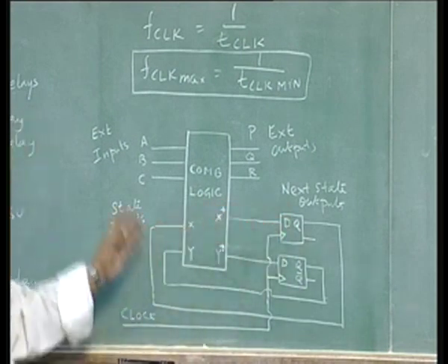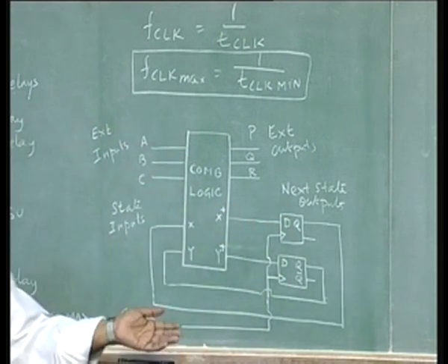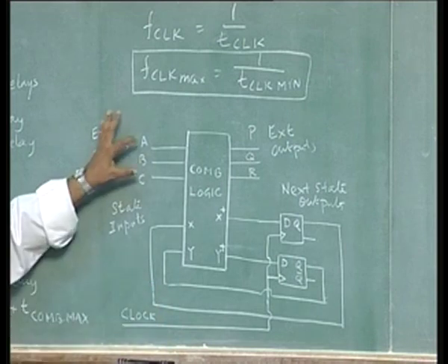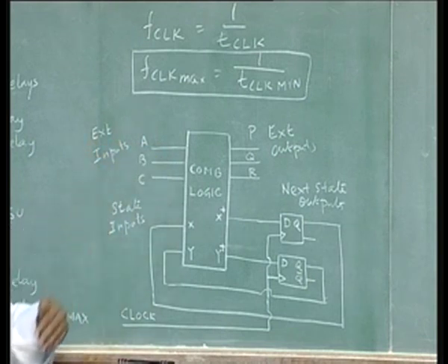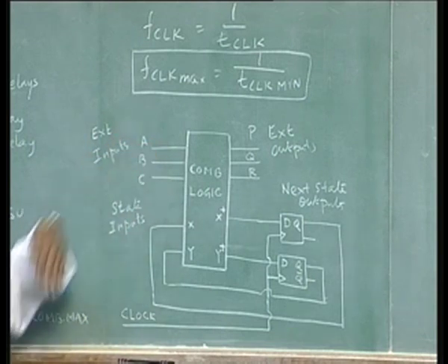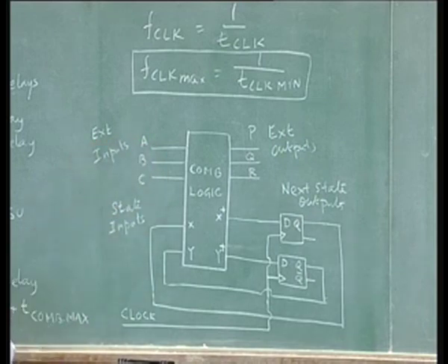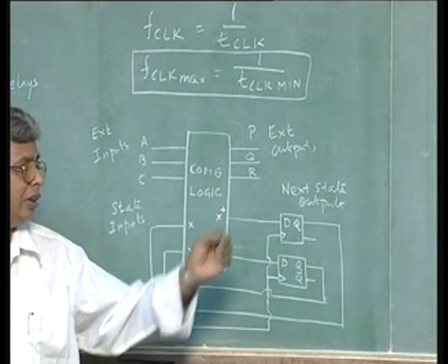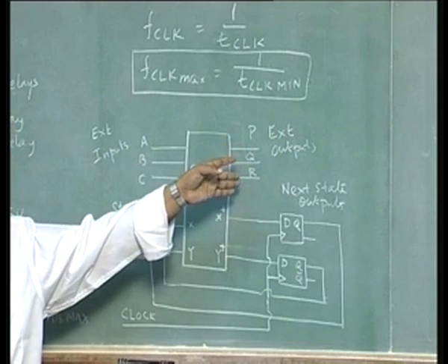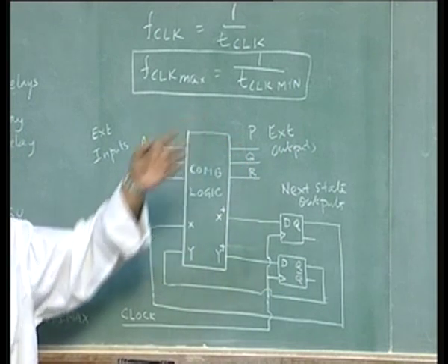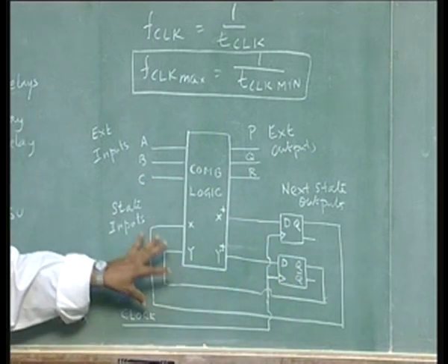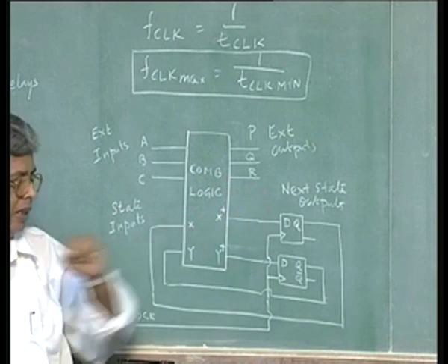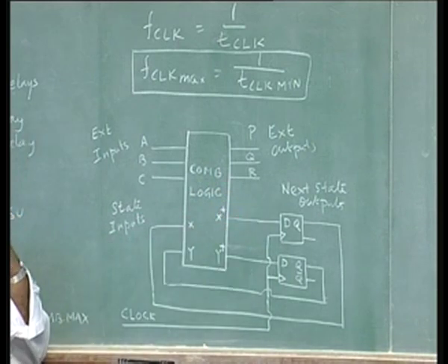That is why now this whole thing becomes a sequential circuit, which has some practical meaning, with A, B, C as the inputs. Maybe in a traffic light controller situation, this can be the different sensors or timing elements, and it could be the state in which the circuit passes through, and this can be different lights, red, green, yellow lights which are required in the traffic intersection. So, this is how you have a normal sequential circuit or any standard digital system configured or defined.